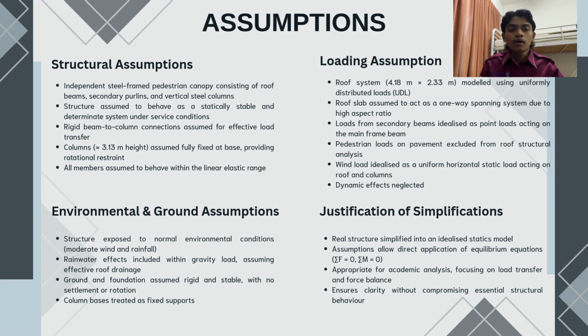In terms of environmental and ground conditions, the structure is assumed to be exposed only to normal weather conditions, with effective drainage preventing excessive water accumulation on the roof. The ground is assumed to be rigid and stable, allowing the column base to be treated as a fixed support without settlement or rotation.